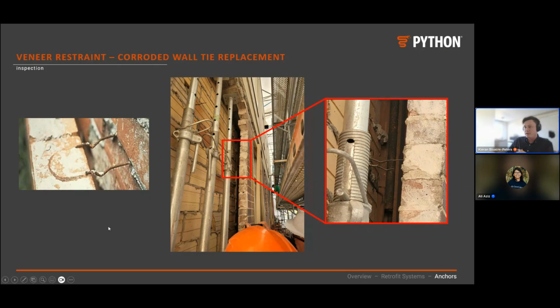As you'll know, with masonry veneer construction, especially with double brick walls, the intention of those double brick walls is to provide a moisture barrier to the buildings, and so you do get significant moisture buildup inside these cavities. All that they really used to tie the 2 layers of masonry together in original construction were flexible wire ties with no corrosion protection on them. As a result, they generally tend to be corroded, and it's sensible to assume as such in your design if you can't inspect them sufficiently.